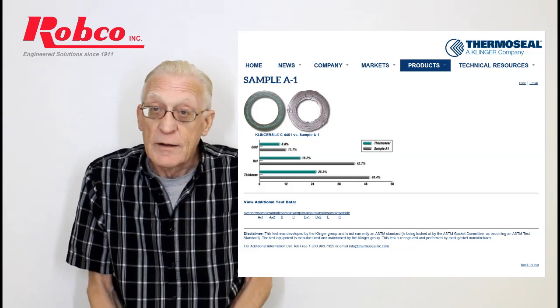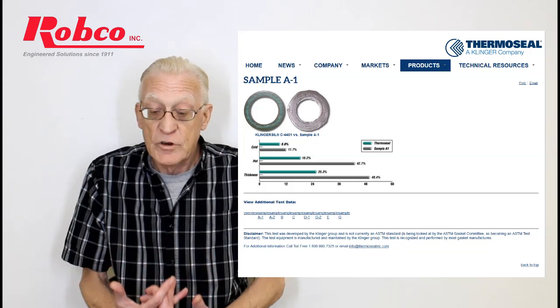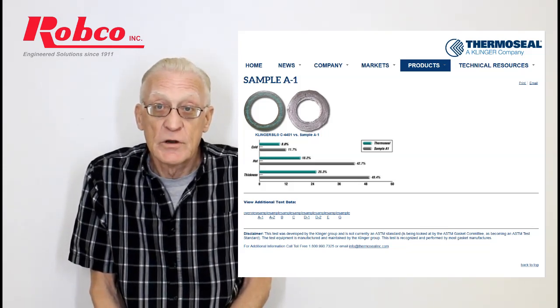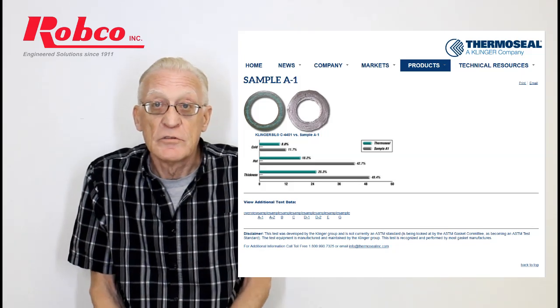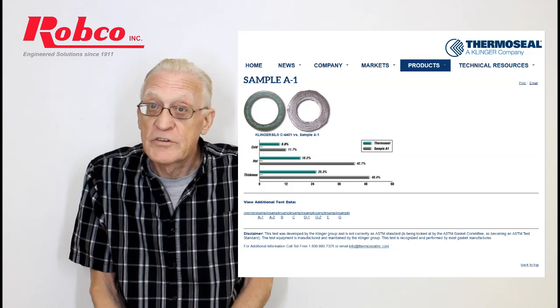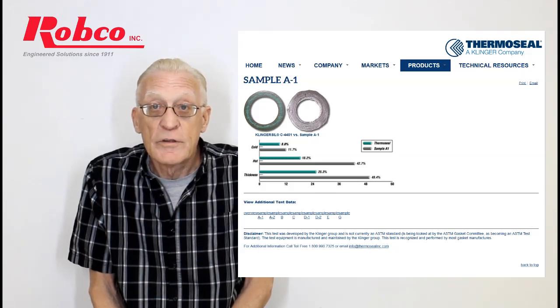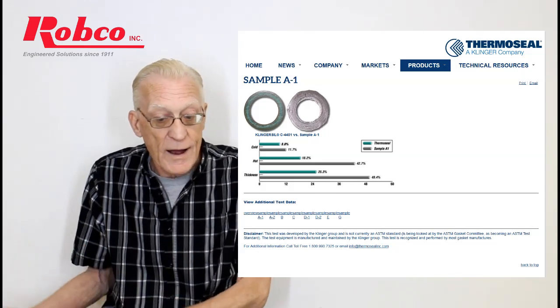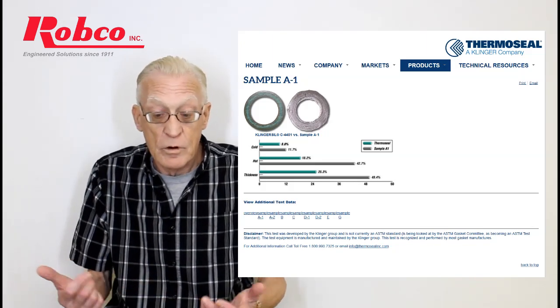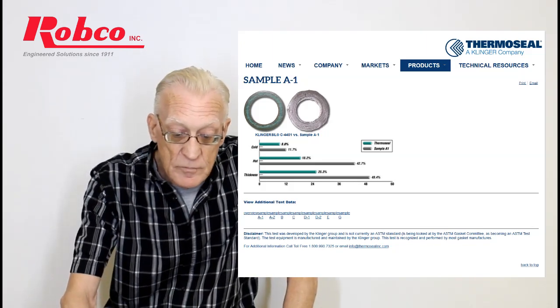This material, in the overall, in the average, 48%, almost 50% thickness loss. It just crushed out. You want that gasket? No, but they all look the same. They're all the same color. How do you know the difference? Well, you can go back to ASTM, DIN, or the actual Klinger hot compression testing.